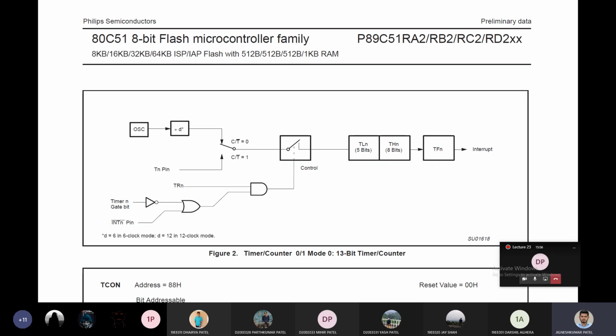The only thing is that rather than having some time delay, now I am counting events, and as we are counting events, the problem will be easier. For example, if I say 1000 microseconds, in that case you have to calculate something, get some numbers, and feed that number into this register. Now we will directly have that number.